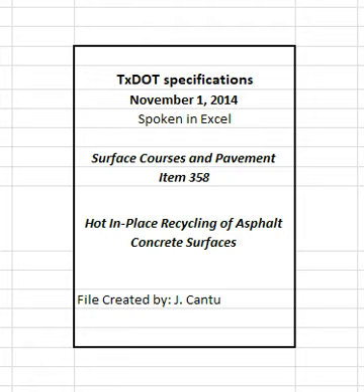The engineer will use the test results from the unsealed core if the sealed core yields a higher specific gravity than the unsealed core. When the in-place air voids exceed the range of 3.8% and 8.5%, take immediate corrective action to bring the operation within these tolerances. The engineer may suspend operations or require removal and replacement if the in-place air voids are less than 2.7% or greater than 9.9%. The engineer will allow paving to resume when the proposed corrective action is likely to yield between 3.8% and 8.5% in-place air voids.